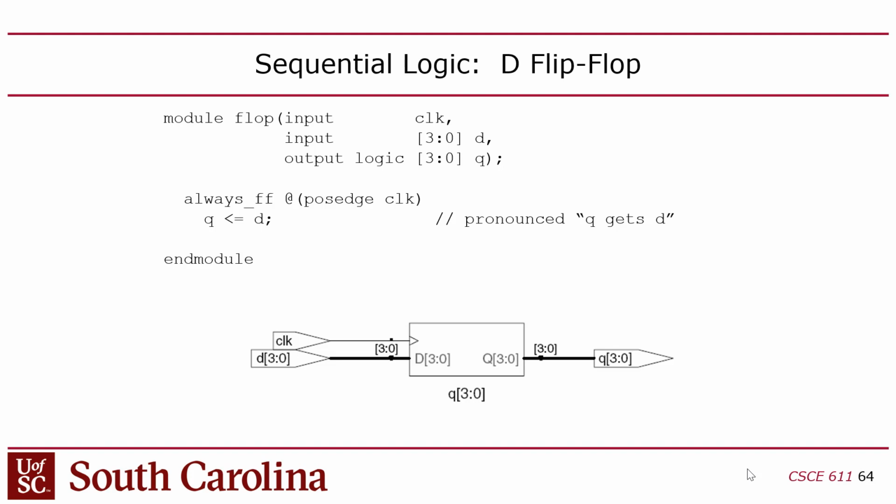So if you set stall fetch now, then that signal will propagate to the next cycle, and one cycle into the future it will be called stall execute, at which point the control unit will have communicated a signal forward in time. It sends a message to the future, essentially: note to self, when you get the next instruction, kill it, because this is a branch. I took the branch, but it's too late. If I'm executing the branch, I'm already fetching the next instruction, so it's too late to do anything about it now. So in the future, kill that instruction when it comes into the execute stage. This is the way that you would create that.